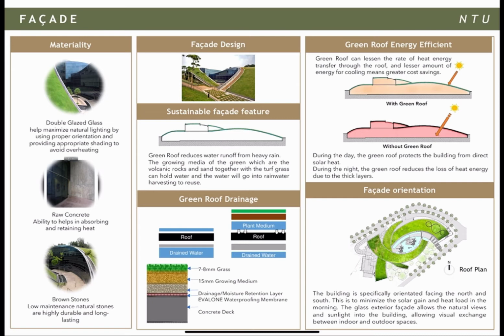For the facade orientation, the building is specifically orientated facing the north and south. This is to minimize the solar gain and heat loss in the morning, and the glass interior facade allows natural views and sunlight into the building, allowing visual exchange between indoor and outdoor spaces.